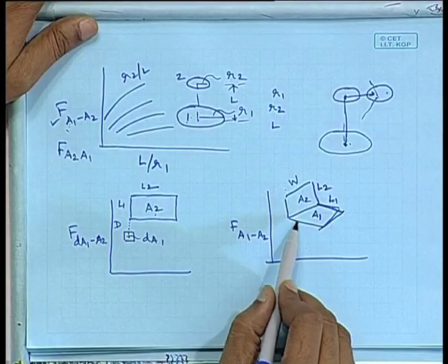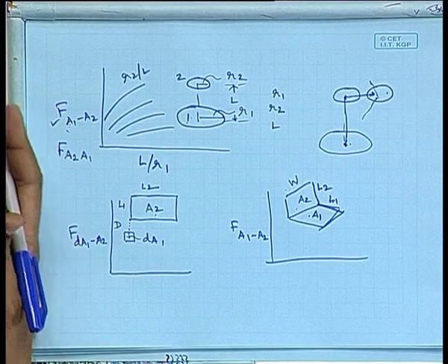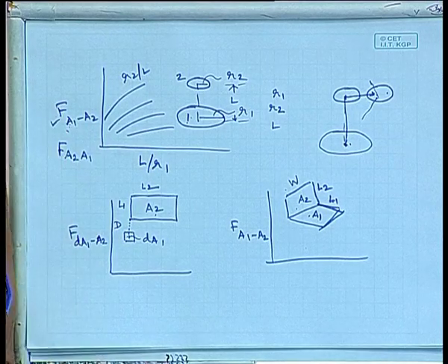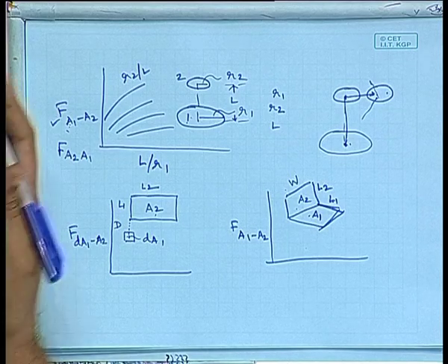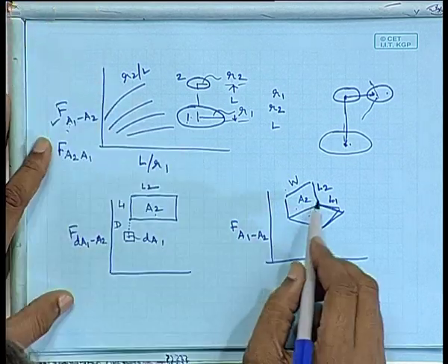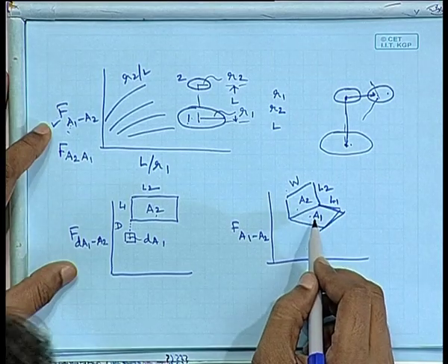out the view factors for many of the situations which we deal with, because you can directly see that this is a case of two furnace walls in contact with each other, isn't it? If you have a rectangular furnace and two sides of it make a 90-degree angle, they are two rectangular surfaces in contact with each other.